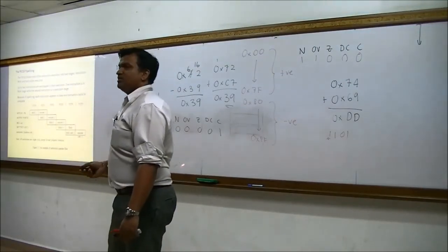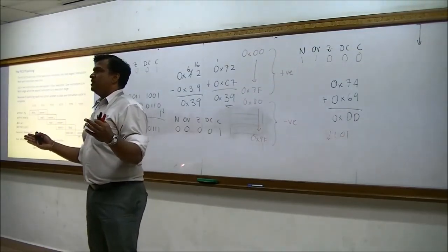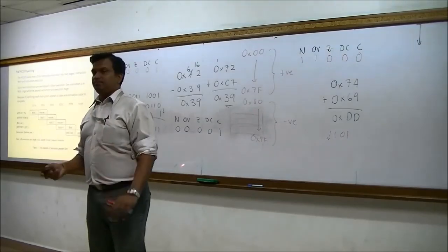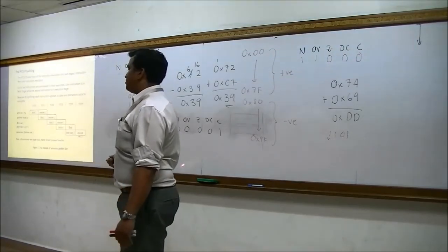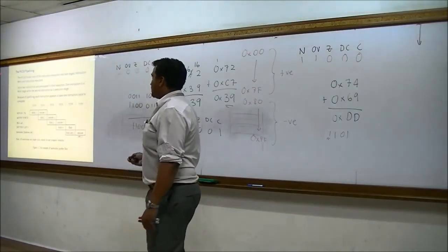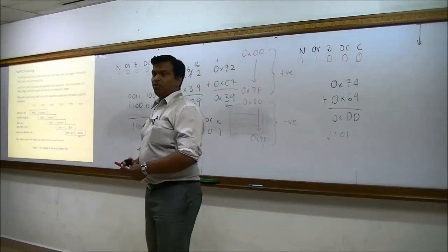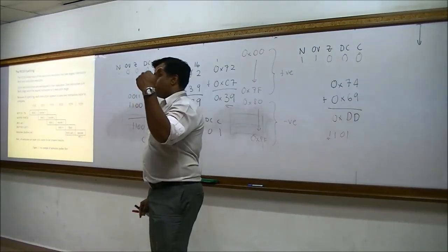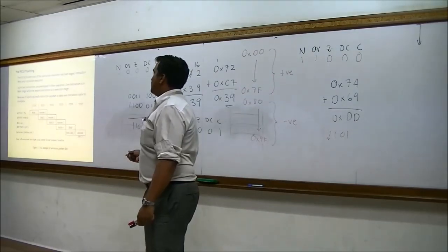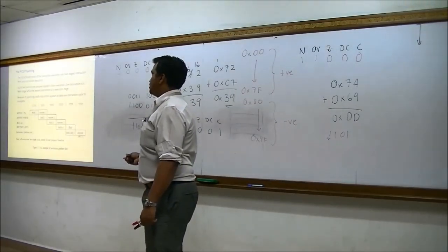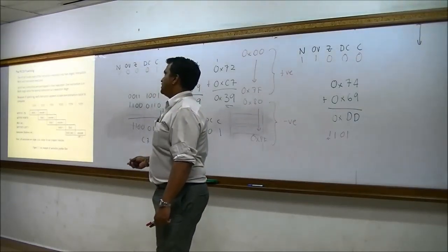We come across this term pipelining. We said that the separation of program memory and data memory allows us to implement this pipelining. So what is pipelining? I've already explained this, but here we have a diagram to illustrate. PIC can divide most instruction execution into 2 stages, like I mentioned before: instruction fetch and instruction execution. One instruction is in fetch while the second instruction is in the execution stage. Because of pipelining, each instruction appears to take one instruction cycle to complete.